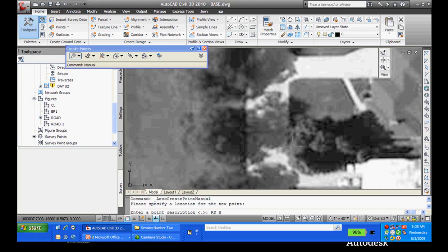Say RD begin. So, and you know what? Let's do this. I'm going to throw some offsets in here too. RD, maybe a horizontal offset. I'm going to go to the left now. So negative 0.5. And I'm not going to worry about verticals. We'll just make it easy for right now, negative 1. So I'll just have a couple lines being offset to my left.